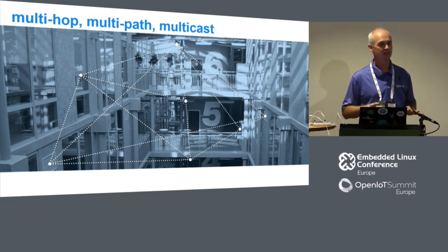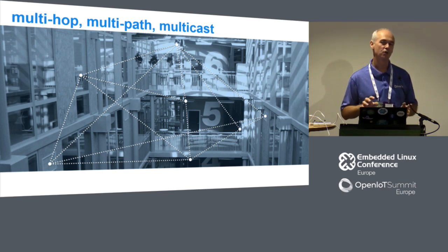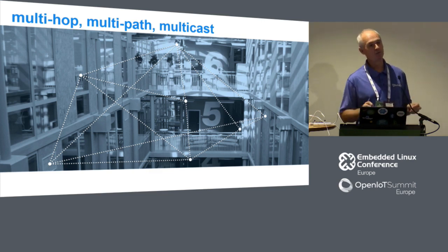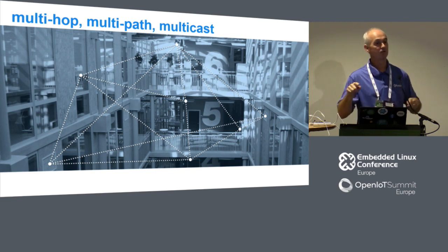So reliability in complex environments like buildings is quite tough to achieve. There are a variety of mechanisms and strategies all aimed at achieving highly reliable communication in Bluetooth Mesh. Don't have time to talk about them all, but one of the primary ones is multipath. And the way multipath works is when a device transmits a message, it's all message oriented, provided you've done a teeny bit of network design and got some things right, copies of that message will travel via different paths through the network to the destination.